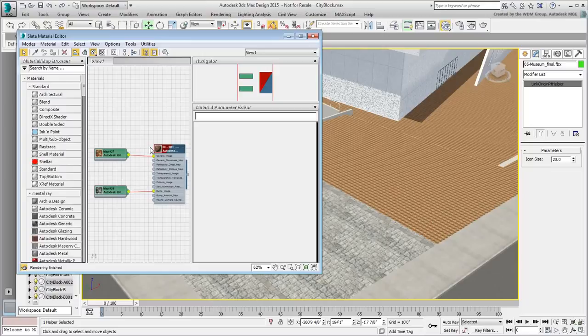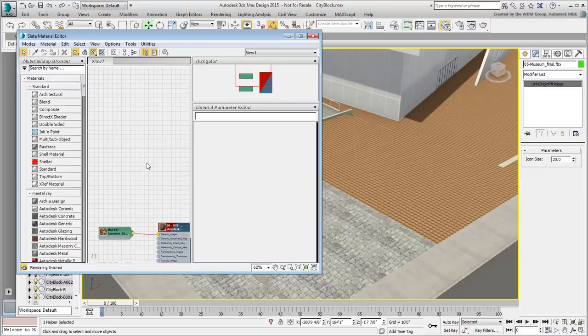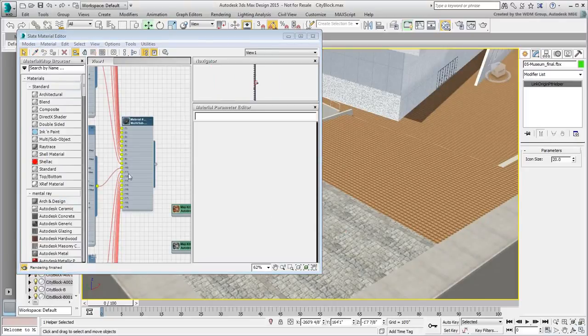The material appears, but the scale is too small. That's not an issue since you are planning to replace it. In the material editor, ensure the option Move Children is enabled and move the material to the side to make space. Use Pick Material again, but this time sample the gray pavers.